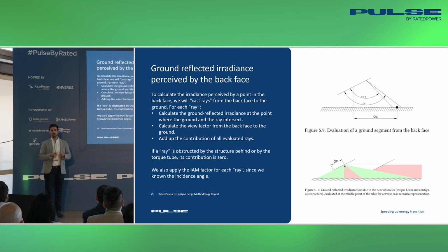Second, PV modules are supposed to absorb sunlight, so there shouldn't be much energy coming back, right? And we want to keep the energy balance correct. And third, modules have things like anti-reflection coatings and different glass properties, which would also be very difficult to model. So we neglect them, and it's mostly fine. Yeah, so we are only considering irradiance coming from the ground.